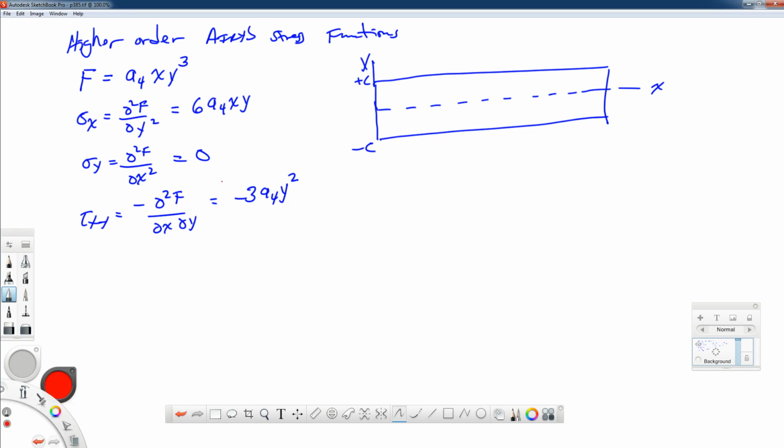All right. We need another dimension. We need a length of this region. So we'll call it that dimension L. And we can plot what the stress fields would look like. The easy one, I guess, may be the sigma x. When we get to x equal to L, sigma x varies linearly with y. And it goes positive and negative.